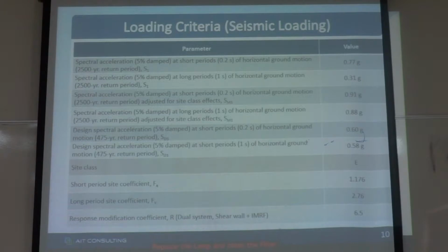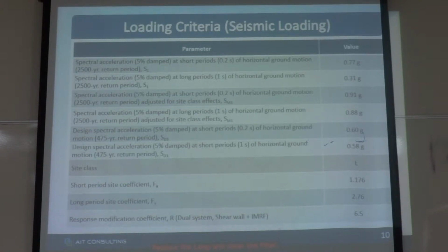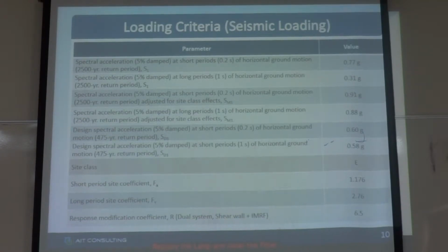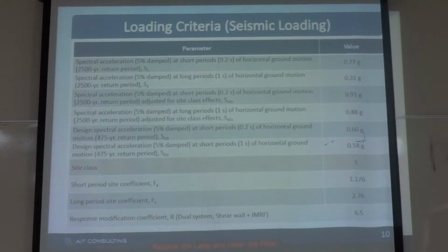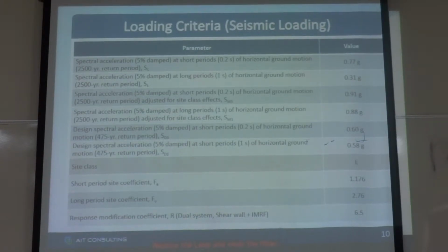But for tall buildings, that's why people start using new technologies and approaches like performance-based design. And for the seismic input, they conduct the seismic hazard assessment for that site and for that building natural period, not directly using the code. The code has only 2 natural periods, and the other natural periods it estimates by formula.